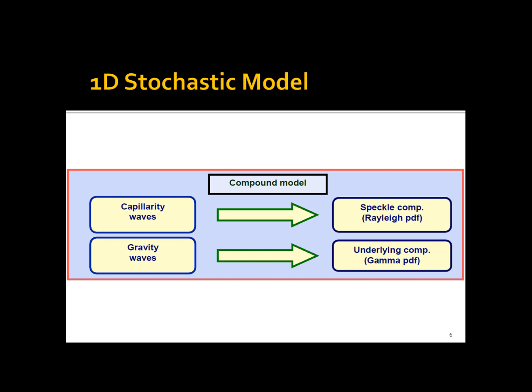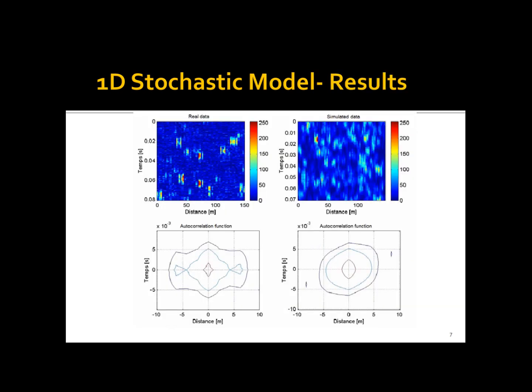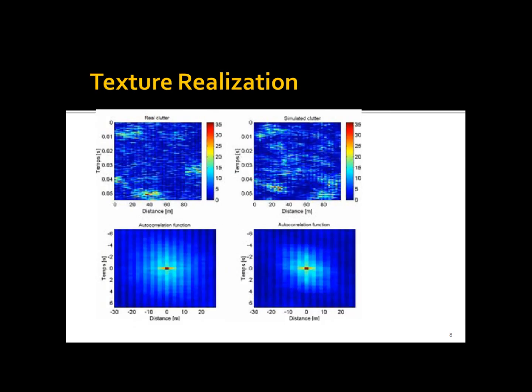The advantage of this model is the compatibility with existing radar processors and detection algorithms. However, this model has been stretched to the limit. It's quite difficult to obtain a valid set of parameters for an assumed PDF from recorded sea clutter samples, leading to poor results. Moreover, it's not logical to describe the sea using only one variable. However, adding more dimensions removes simplicity. In both of the following examples, there is similarity between the real clutter and the simulated one.